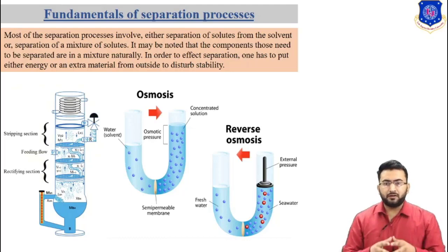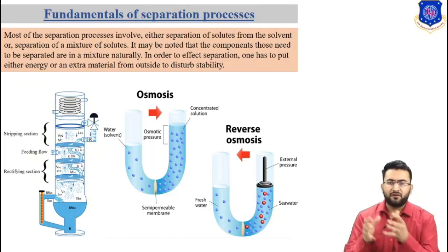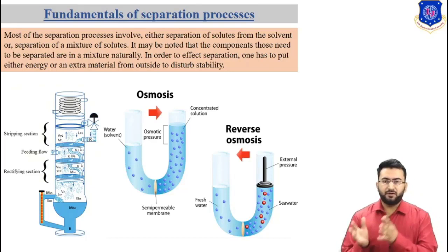Separation processes are integral unit operations in most modern chemical, pharmaceutical and other process plants. Among separation processes, some are standard and conventional, like distillation, absorption, desorption, etc. These processes are quite common, relevant technologies are well developed and well studied. On the other hand, advanced separation processes are divided into equilibrium and rate governing separation processes. In equilibrium governed separation processes, the product phases are in equilibrium with the inlet phase. Conventional processes such as distillation, absorption, adsorption, and extraction are based on equilibrium distribution.